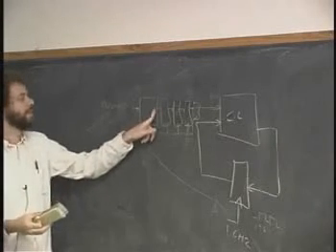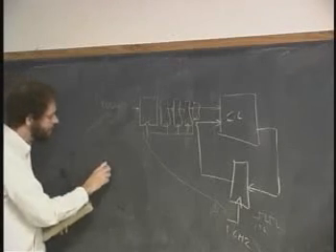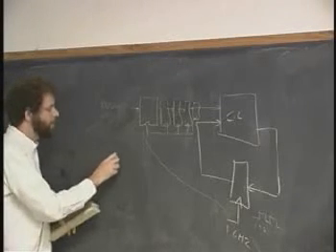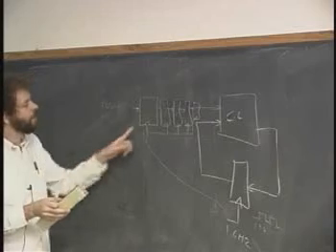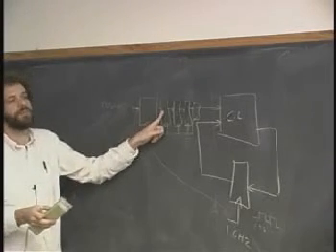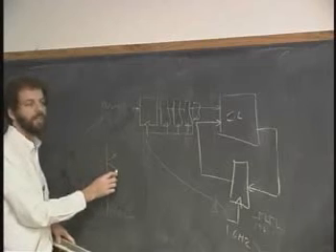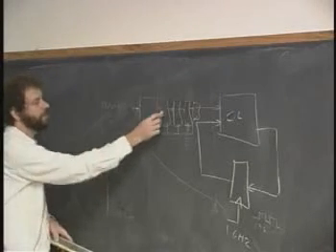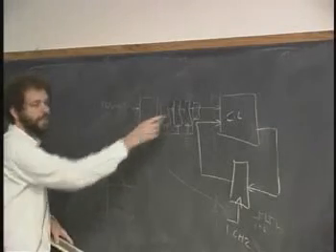But it is lower than the probability that this thing is somewhere in the middle, because it has had some time to try to converge one way or the other, to move the donkey towards one bale of hay or the other. Then we pass off the job to the next flip-flop. We say, okay, I've moved the voltage this far, and now I pass the job on to you. And now you move the voltage a little further. Now I pass the job on to the next one.